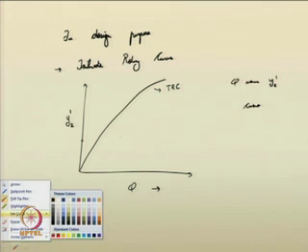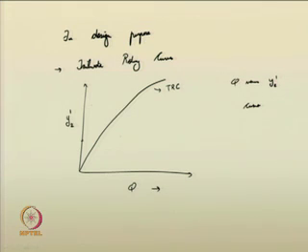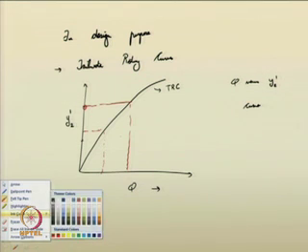If this is given there, one can easily identify. Say for example, at a particular time I have a depth here, some value here. The corresponding discharge can be easily identified here, right. If I have another depth of tailwater at this location at some other time, you can easily suggest the magnitude of discharge corresponding to it. So, using this tailwater rating curve you can do the design. A similar type of rating curve you need to employ for jumps also.